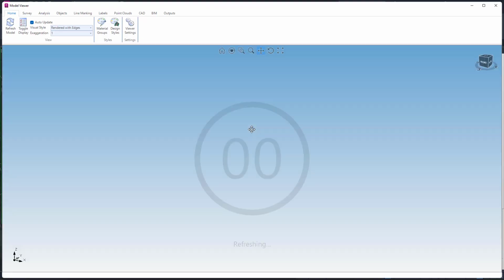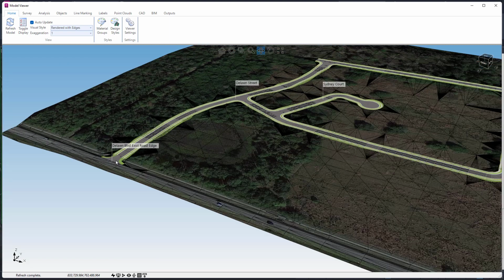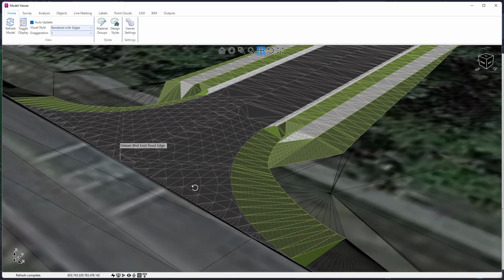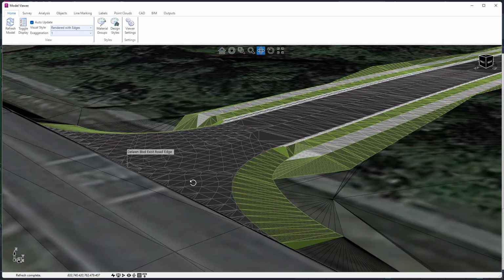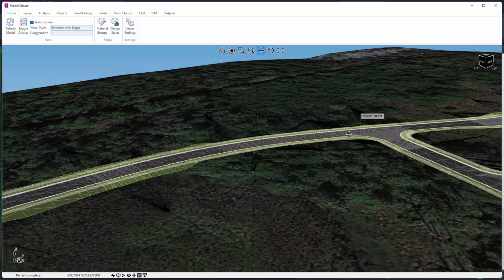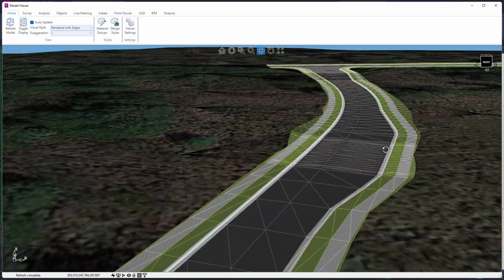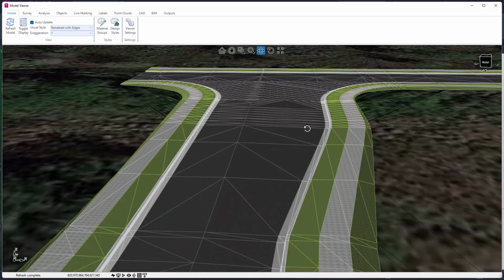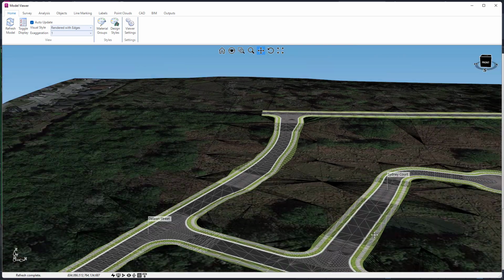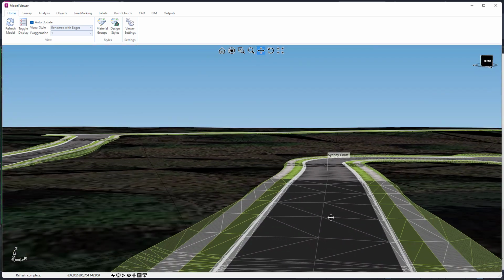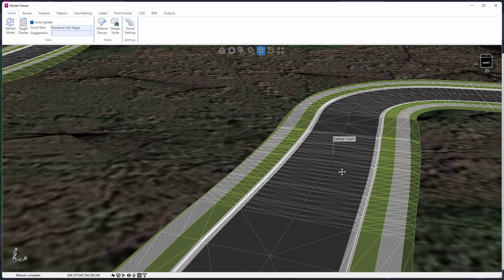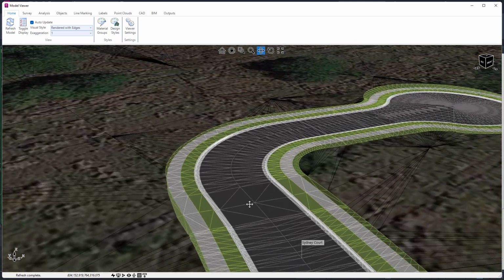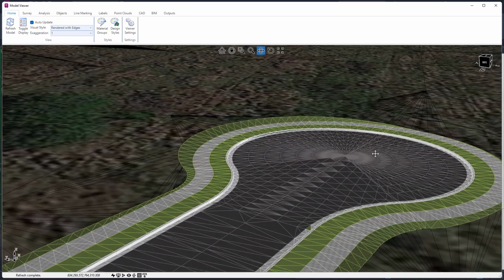Because we've been using Total Model, it would have been automatically updating in the background, meaning that what we're going to see is the entirety of our design. So first of all, there is the connection now between DeLorme Boulevard and the existing road edge. We can now have a look further to the north, and we can actually see our widening going on for the bus bay, and even further north we've got the widening around the intersection. If we have a look at Sydney Court, we can actually see our slightly wider road there being applied, and then we can see our transition, which I think was around 87 feet, going back into the slightly narrower road all the way through, followed by the cul-de-sac.